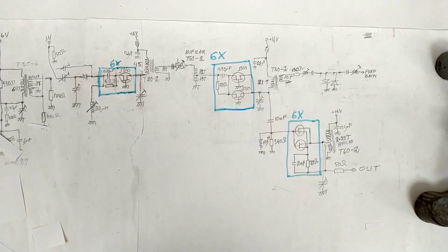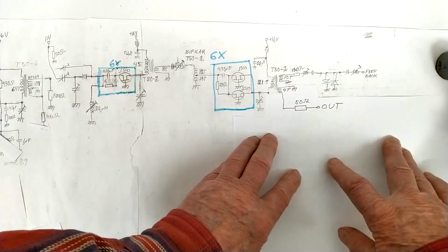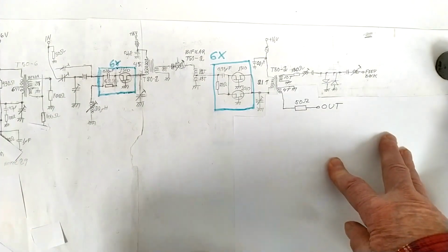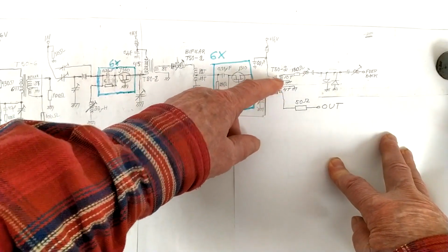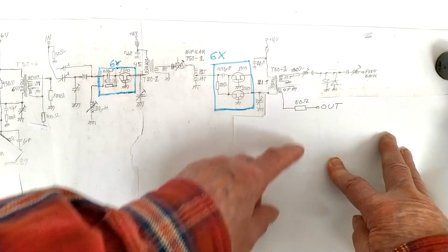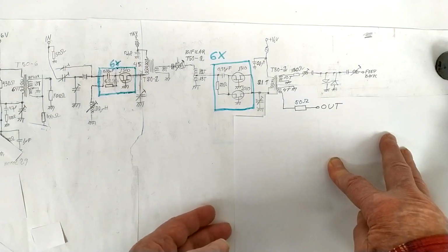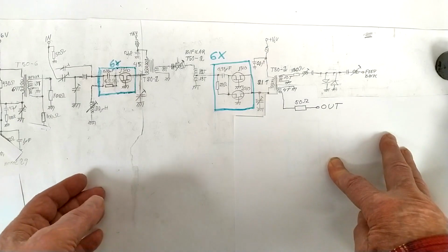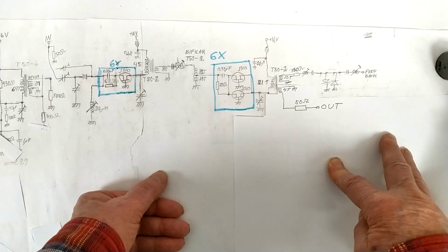I have disconnected the output amplifier, this one, and now I take the output from a 4-turn winding on this core and a 50 ohm resistor in series. The result on the noise is not visible, very small differences, but the power is about 10 decibels lower.